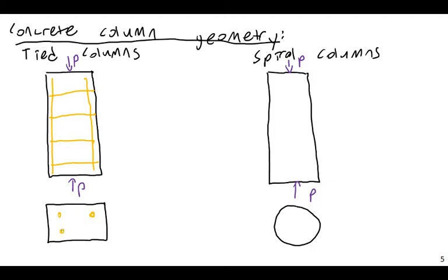You have your major axial reinforcement, and then you have a tie going all the way around, similar to the idea of shear stirrups, although not exactly the same thing. You have just a piece of number 3 or number 4 bar wrapping its way around the section, providing confinement and helping to prevent buckling.